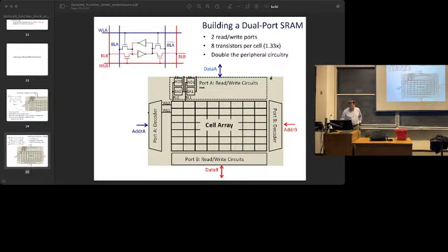You're saying what if you're trying to write the same row at the same time? So that is basically documented in the vendor data sheets as don't do this. If you try to write 2 different values, so basically the question is, what if you send in address 12 here, and you also send in address 12 here, so they both activate their word lines for the same row, and they've both been told to do a write, and the data is different.